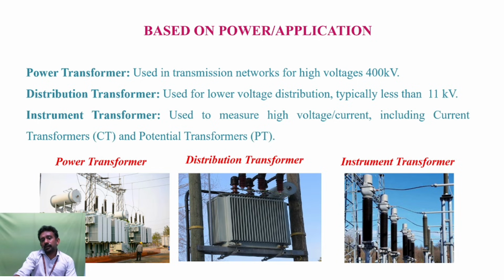And coming to the categorization of transformers based on power application, it is categorized into three types: power transformer, distribution transformer, and instrument transformer. Power transformers are used in transmission networks where the voltages are very high, around 400 kilovolt or more.